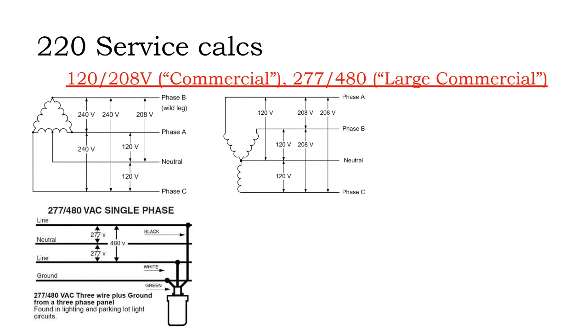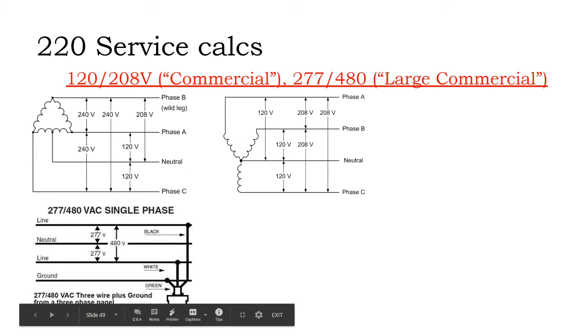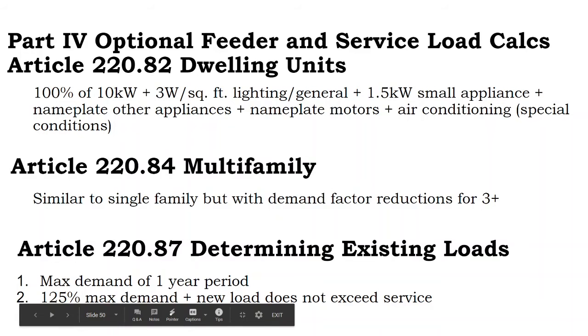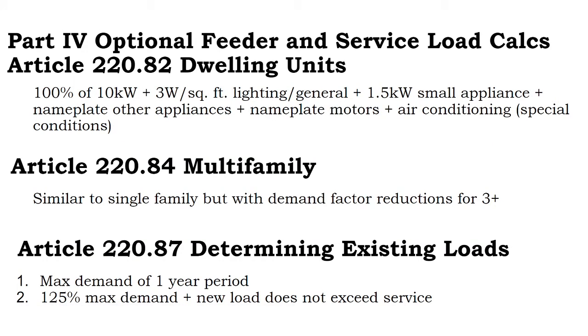At the commercial level, they have a delta service and a Y service, and that literally has to do with the windings inside that transformer forming a delta triangle or a Y. And so you'll have to get a different inverter for each custom electric service, or sometimes there are dip switches on the inverters that you can select to make one 120 volt or 120/240 or just 240, but that's more rare.